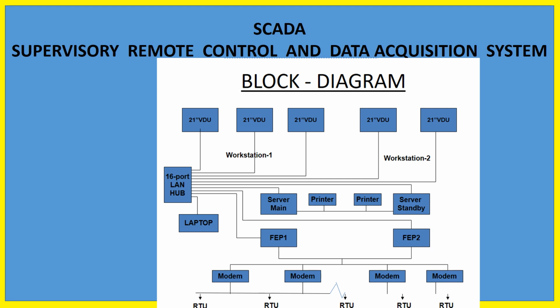Now, to identify this equipment, we have to give an initial code, then identify the switching post, then the name of the particular equipment, that means a particular CB or interrupter, and then what you will do, close or open, and then an ending code. A starting code and an ending code will confirm that this code is complete.